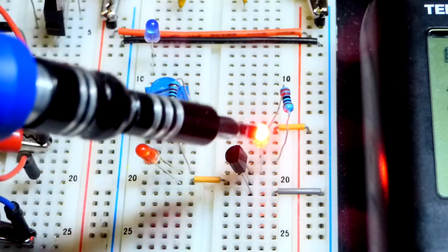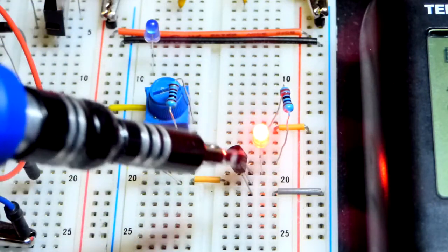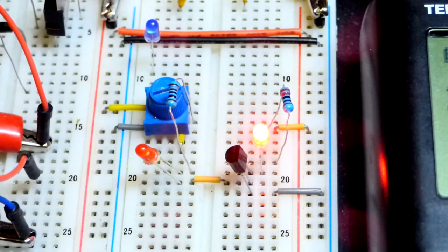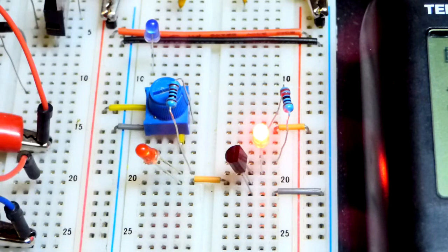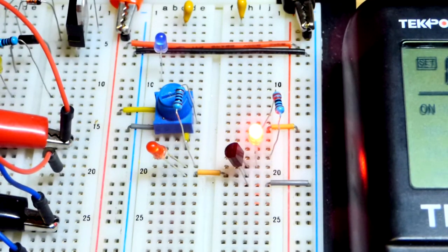And once that current gets to whatever the load needs, then it just stops limiting current. The load limits the current from there. In any case, the main thing is a very small current allows a lot more current. Whenever you're studying transistor circuits, that's the basic principle. Not terribly complex once you understand it. So hope you do now.